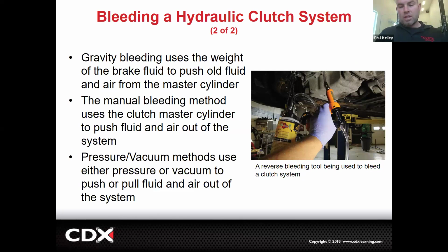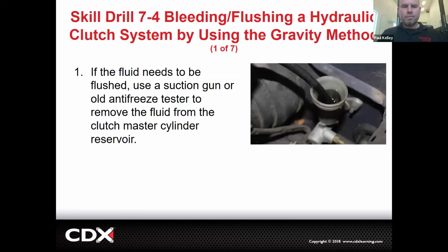This is another thing that they've been doing, and I'm thinking about getting one. This is a reverse bleeder. This actually pulls from the brake container, sucks it up in a hose, and you pump pure brake fluid in the bleeder and you push it all the way up to the master cylinder. That's a great way to get all the air out. That's also probably going to make it so that the master cylinder overflows and you get brake fluid all over. And that's how I lost my hair. But also be careful of the paint. So if it gets to that point, you better cap that sucker and get it down and degrease it and spray it because it'll mess the paint up, right? So there's a couple different methods there.